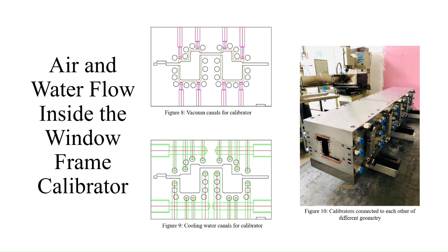After leaving the extrusion mold, the profile immediately enters the calibrator, which is shown in this slide. Here, vacuum pressure, along with controlled air and water flow, is applied to stabilize the profile geometry. The vacuum pulls the hot PVC profile against the calibrator surfaces, fixing its external dimensions. This step is especially critical because the material is still soft and highly sensitive to deformation.